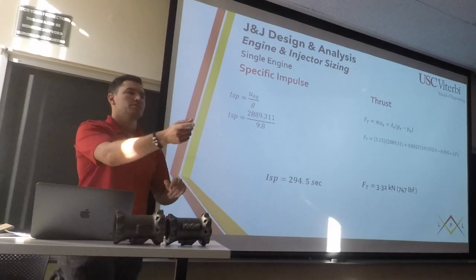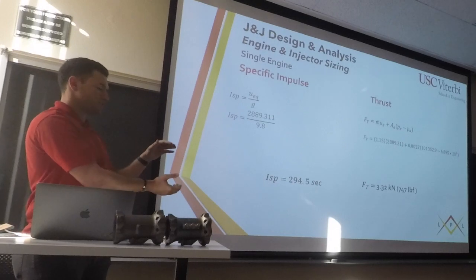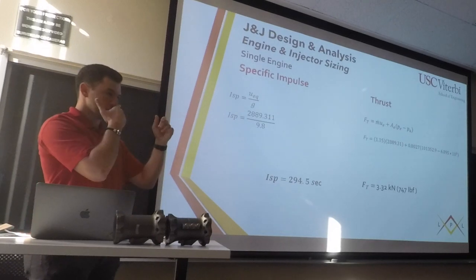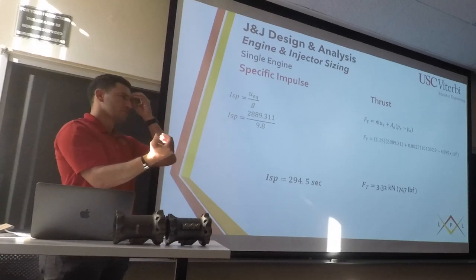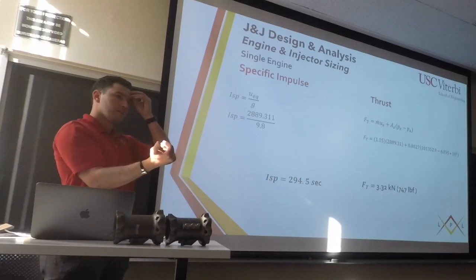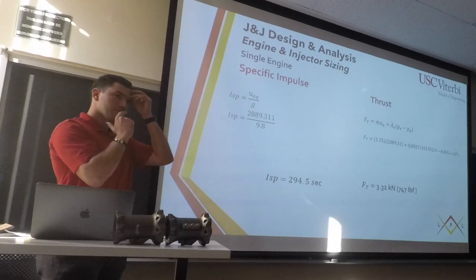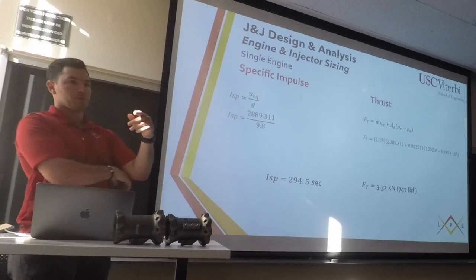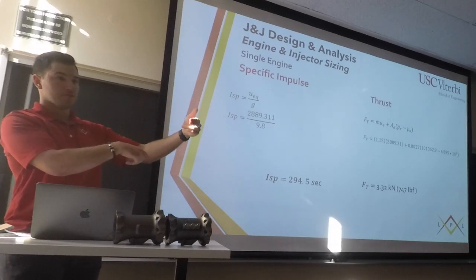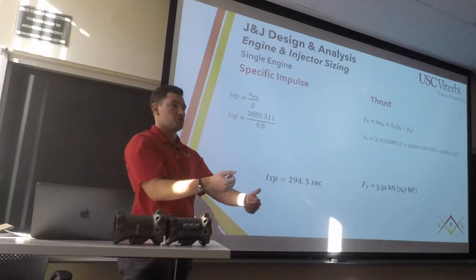So what ends up happening, if you look up a shock wave, you have overexpanded, meaning that it's expanded too much, that it's still really low, and the ambient pressure is higher than the exit pressure, and the ambient pressure will generate a shock wave. Yeah, because it wants the pressure to increase. Across a shock wave, the pressure jumps.